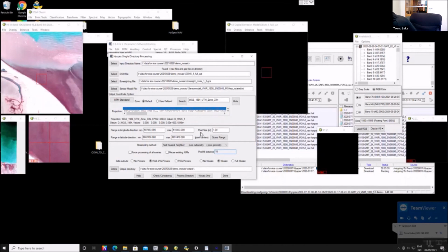It will look for a pixel within 3 pixels away. So if it doesn't find a pixel within 3 pixels, that can be, let's say your aircraft pitches a lot, then the field of view on ground can move very fast, and you might not have a center coordinate of a pixel closer than 3 pixels. Then you will get a dark pixel. As you saw, this image was very nice. It was flown stably with very low standard deviation, so 3 would have been okay to use here as well.